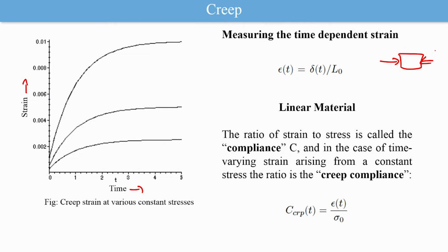Okay, the rate at which you apply the load or the F. If you change this, like you apply force faster or you apply the force slower, you will actually get different strains when it comes to this kind of materials such as tissues or polymers.